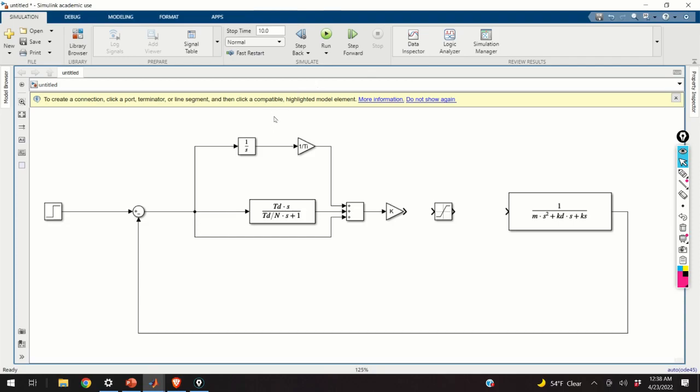Next, let us connect the saturation to other parts of our diagram. So I'll simply draw an arrow by connecting these two parts, and here it is. My saturation is connected with other parts of the diagram. When you create your block diagram or Simulink model, it's always a good practice to name certain parts. So this block can be called saturation limits or actuator saturation.